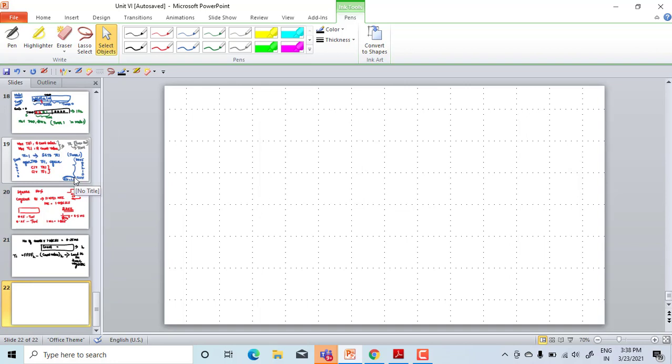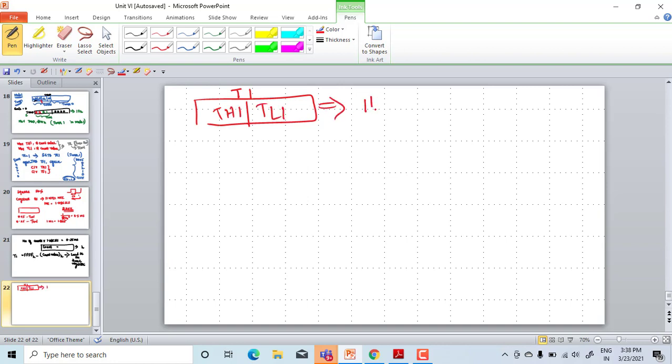This timer 0 can be used as a 16-bit timer. Okay, as I said earlier. Now we are using both. For example, in this example we have used a timer 1 register, meaning TH1 and TL1 both are used for loading up the 16-bit value. Okay, 16-bit value. Whereas this is nothing but a 16-bit timer or counter register.